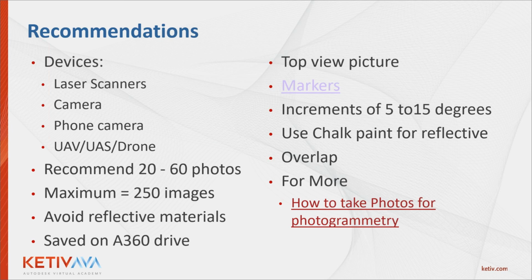Exactly. That was one thing that I kept running into where I wasn't getting the fine detail. What you want to do is make sure at least 40% of the image overlaps. Yep, that'll give you a better result. Exactly. Zooming in and zooming out of certain areas too. And don't worry about holding the camera at different orientations and so on, because the program will end up picking that stuff up. It'll look for surfaces and things like that.